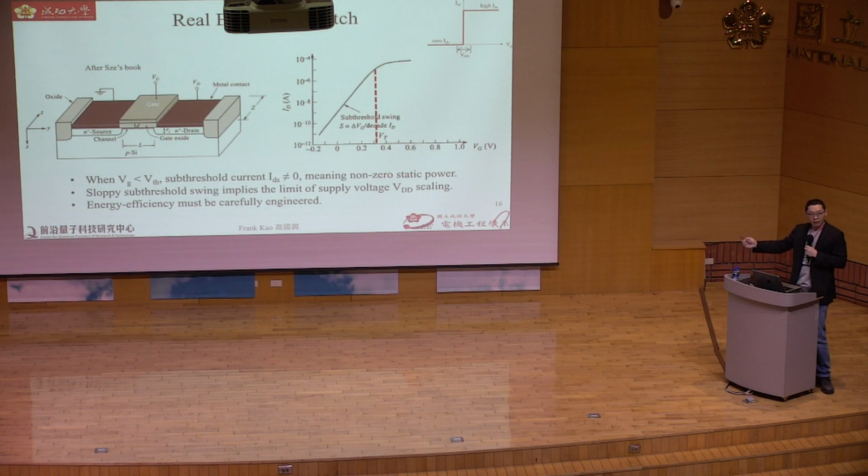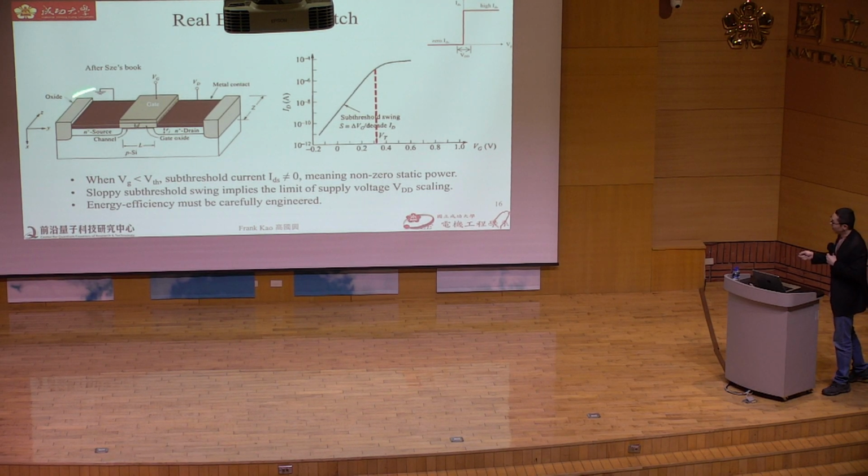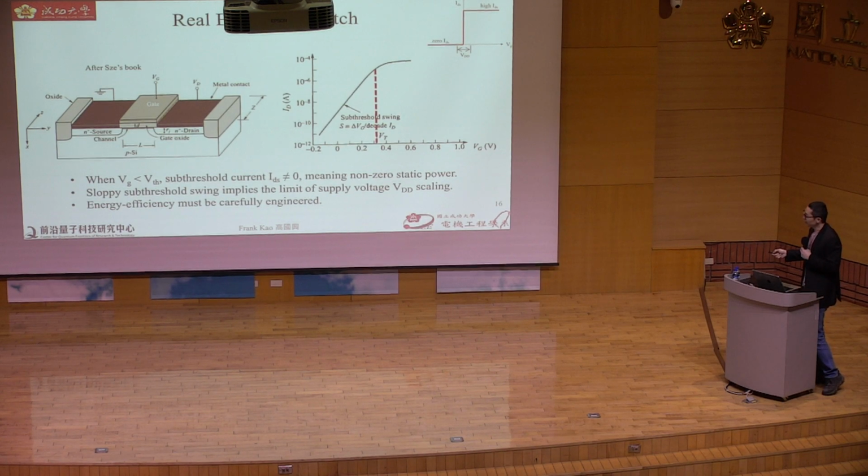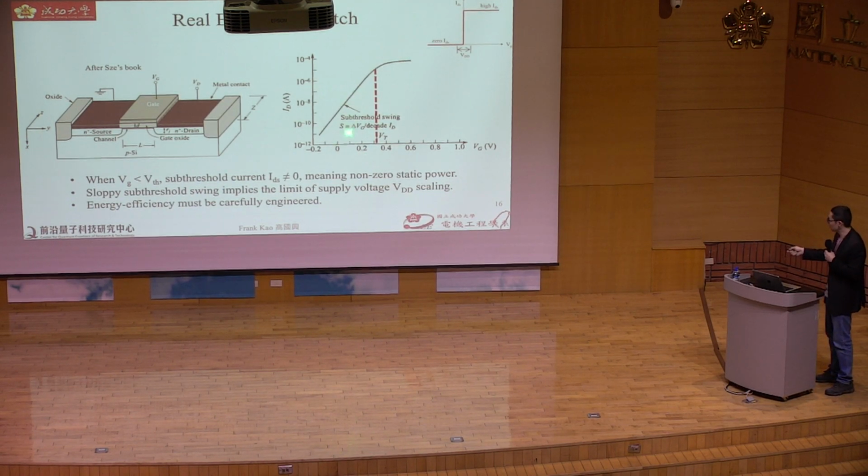But that's ideal. This is the reality. That's the basic device we are using in our cell phone, MOSFET. And this is the IV curve it shows. Instead of this step-like slope, it shows a sloppy subthreshold leakage before you reach your threshold voltage and you're on state. That means before you turn your device on, you already are consuming electrical power in this region.